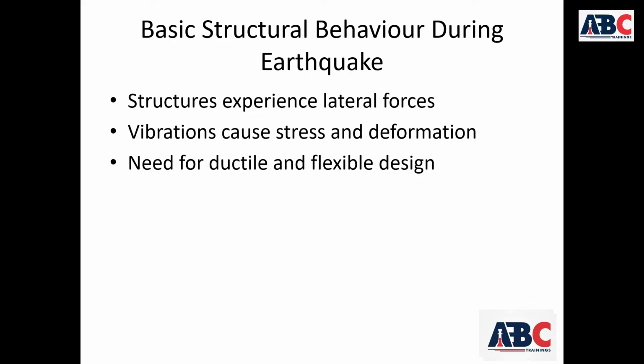This vibration causes bending in beams, shear in columns, and torsion in irregular buildings, cracks in walls, and displacement at the top of buildings. The building starts swaying. This swaying produces internal stresses in structural members.